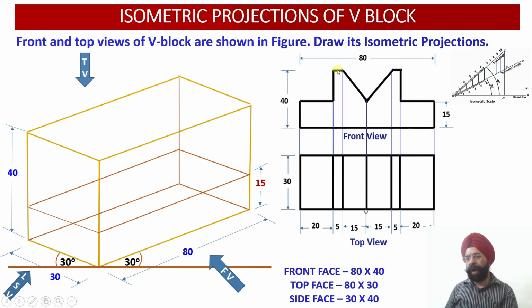That is, this is the upper portion of the shorter web which is vertical, this was horizontal, this is the vertical web over here. Now I have to integrate information of the front view with the top view. In the top view I get the measure of this thickness. So at what distance this web is starting, this portion of the lower part of this component will be straight, and up to which length this will be straight, 20 millimeter. The length of this segment is 20.